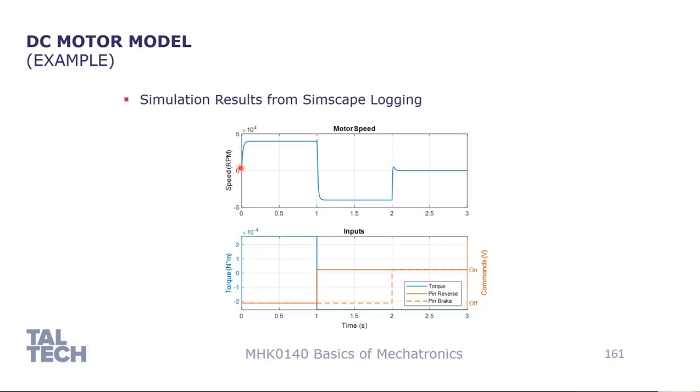So this is an example. You see that the tested motor here is starting to rotate in one direction. It rotates for 1 second in one direction, then it stops, changing the direction. You see how the transient is happening, how long the transient is. In this case, the load is not that big, so the machine needs a little bit of torque just to change, and then after the second it stops, so we can see how it stops and how the command is operated.